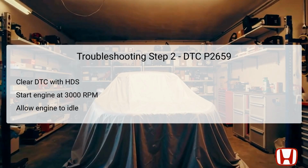In this step, the technician will clear the Diagnostic Trouble Code using the Honda Diagnostic System, HDS. Doing so resets the Engine Control Module, ECM, and erases any previous fault code from memory. Subsequently, the engine should be started and held at 3,000 RPM without load, meaning the vehicle should be in either park or neutral. This specific RPM threshold is significant as it ensures that the oil temperature rises to a point where the oil pressure becomes optimal for operation.